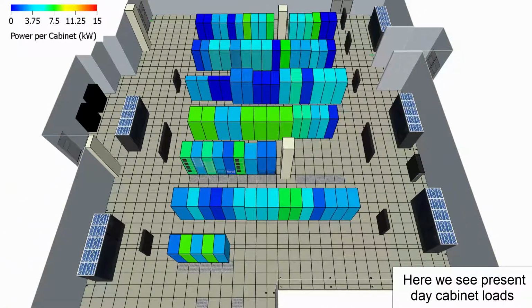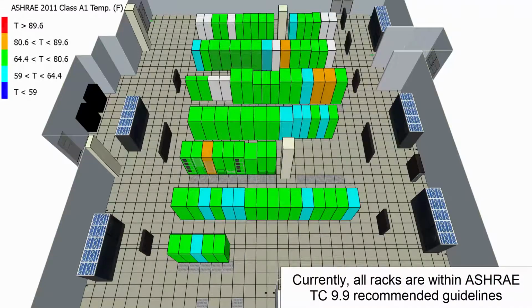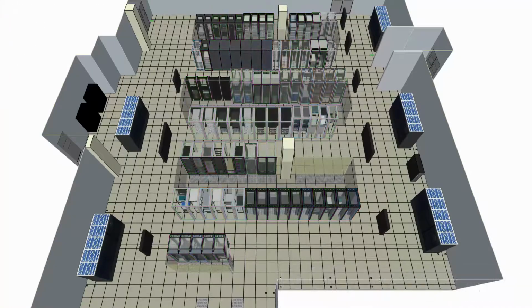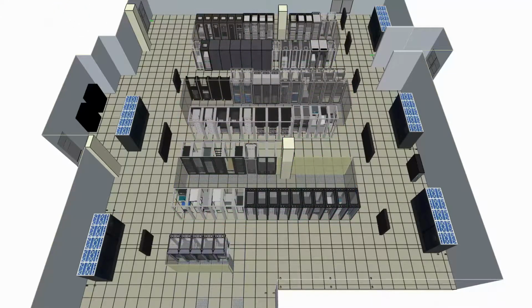This image displays present-day cabinet loads, showing some empty racks and others loaded up to 8 kilowatts. By simulating this configuration, we see that currently all cabinet inlet temperatures are within ASHRAE recommended guidelines. We can also look at design IT limits for each aisle in order to see where there is available power. Aisle 3 appears to be the ideal location for a high-density deployment.